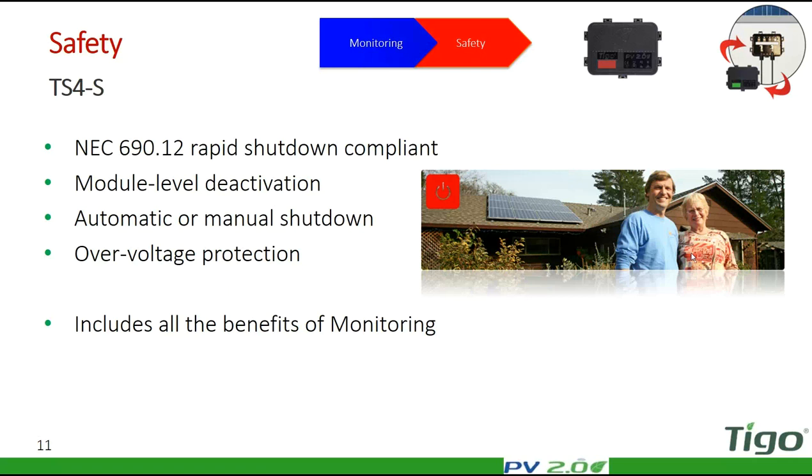And manual, if you push our PV safe, which is our safety disconnect button, you can deactivate the system, or if you take the main AC out, like first responders do in case of an emergency. They take the AC out, both the inverter and the cloud connect, well, our data logger, basically lose the communication, and the TS4 safety and above covers understand that that's a safety hazard.